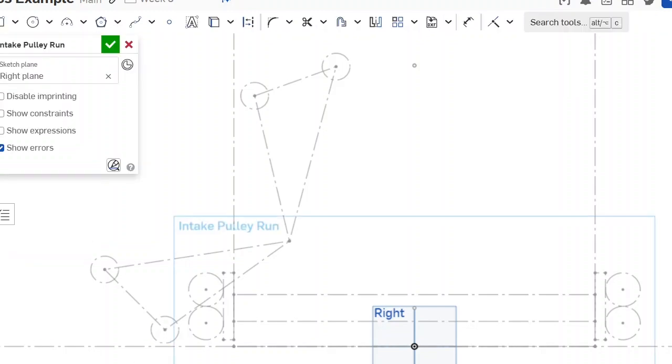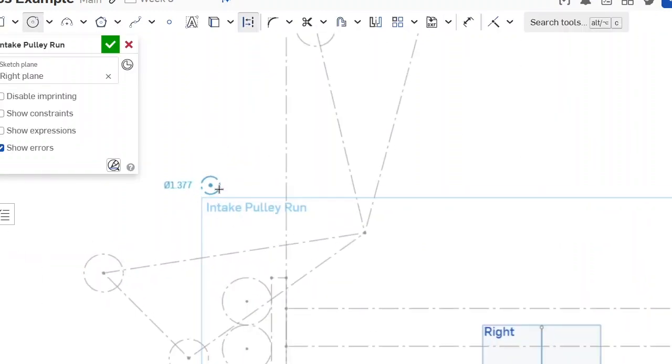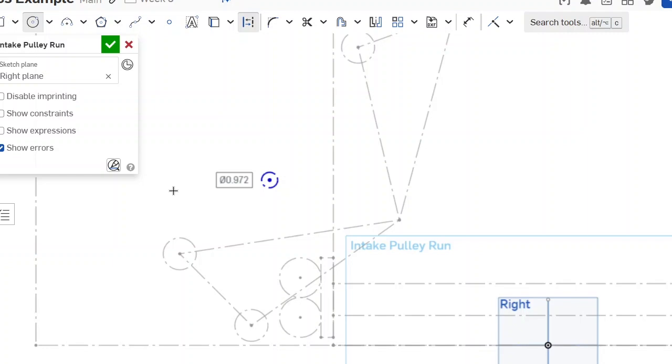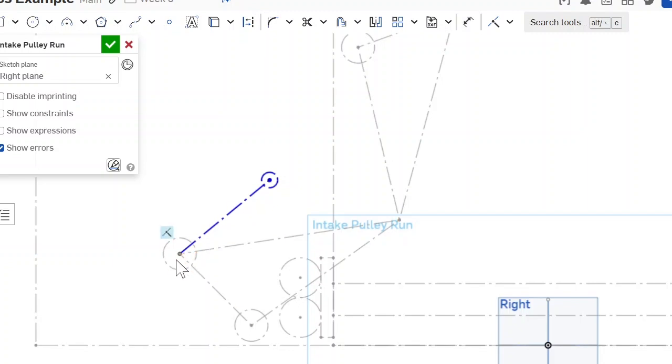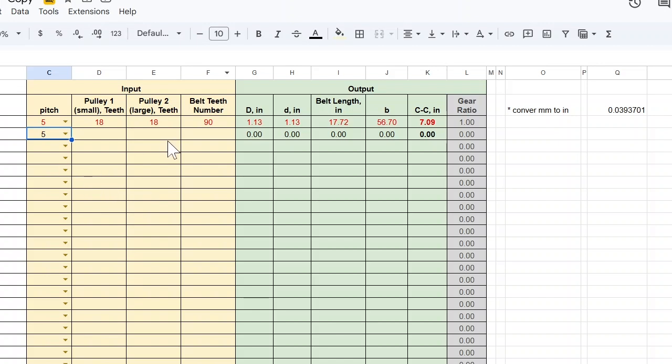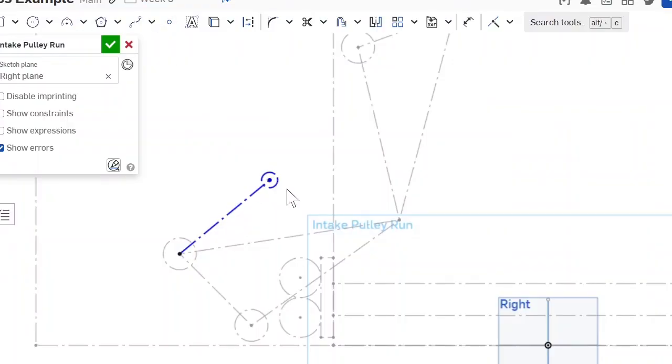On that sketch, I know I'm going to have a motor somewhere. That motor is going to have a shaft, so I'm just going to draw a circle to represent that. And then I'm going to draw a straight line going from that circle to this wheel. Let's say that looking at the belts that we have in shop, we know that we have a 100 tooth belt. Looking at this, generally the motor probably should live close to the pivot, but let's say we want the motor to live somewhere right over here. So we got 7.69 inches.